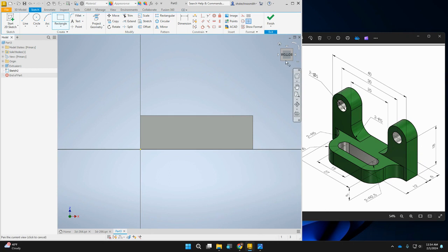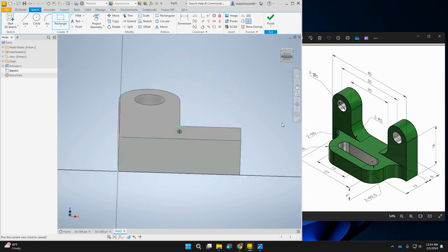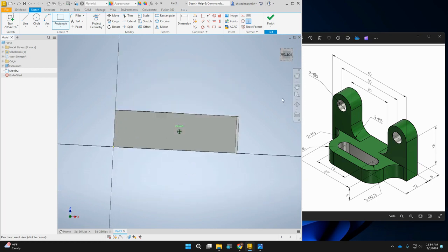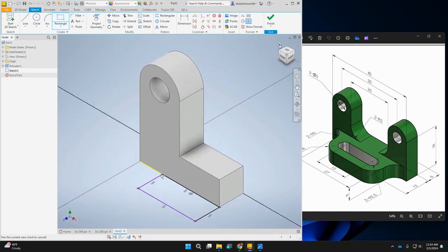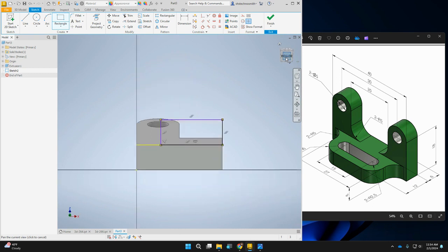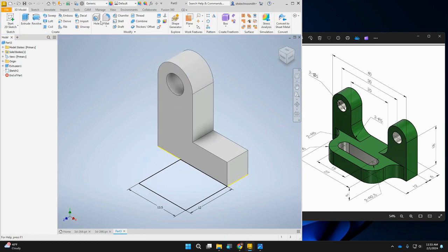All right. So I've rotated this down like that. So this is where I'm kind of looking at. So now I'm going to go like this, and we can see kind of what I'm doing. And so the whole thing all the way across is 27. So to the middle, if you can't do it in your head, we can do 27 divided by 2. And then that sticks out 12. And we'll finish our sketch.